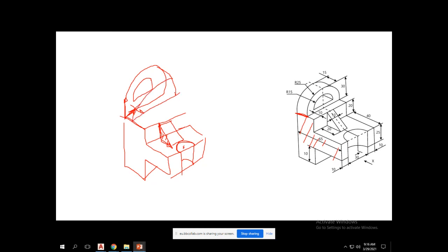That's it. And finally, after we do all these things, guys, what should we do? What should we do? The very last step before the dimensions. Exactly, union. I have to make a union, and then I can add my dimensions at the very last step. Yeah, you extract the edges. It is better to extract the edges, guys, before you make your dimensions. Okay, this is a very good recommendation. Before you think about adding any dimensions in any place, it is better to make extract edges.